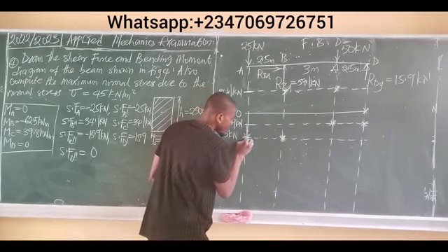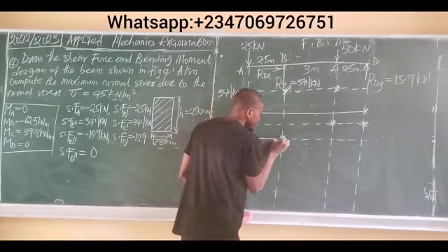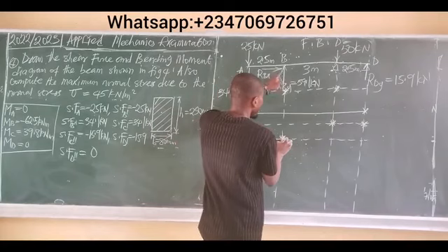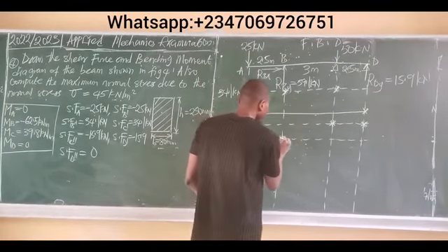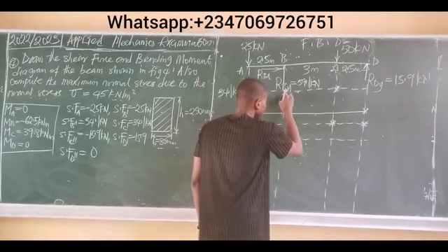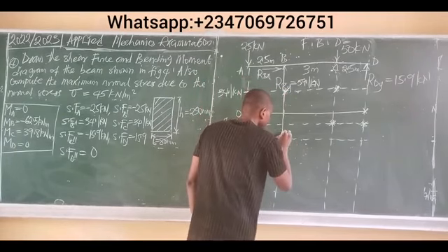Now, this force moves from point A down to point B initially, now encounters an upward force, which gave us shear force at B to be what? 34.1 kilonewtons. You simply use a straight line and you join the 2 points together.